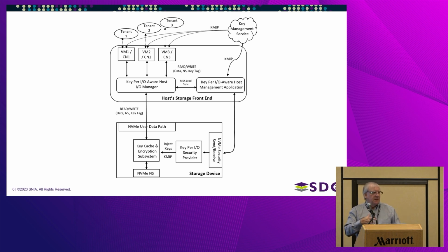So the host has to pass it. The KEK is being used to wrap keys that are coming down. Now once the cache is loaded, you don't really need to worry about the KEK because then you're just using namespace ID. But if you haven't successfully loaded the cache and you go to do I/O, that's an error condition, because the drive says, I don't have any keys.